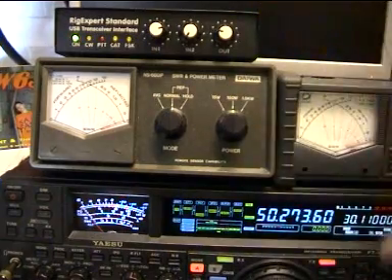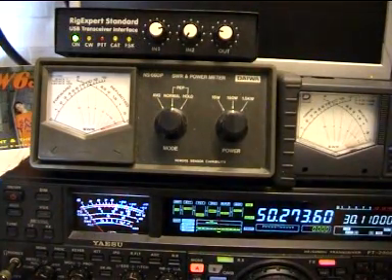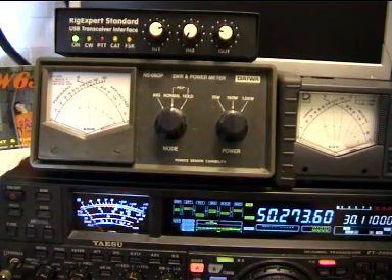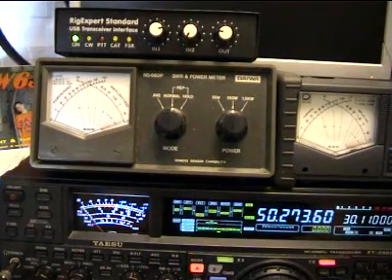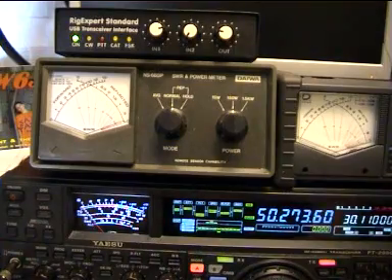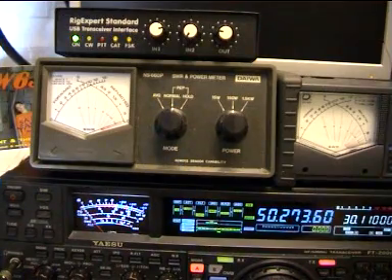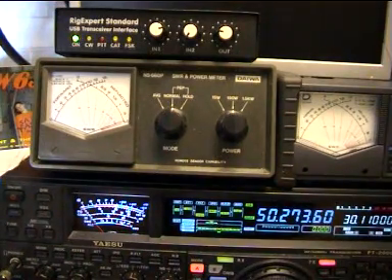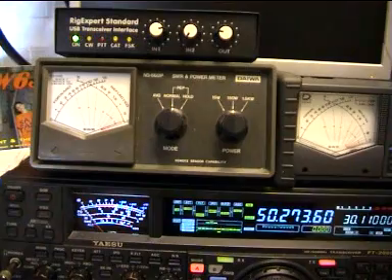Please now take your radio to an unoccupied frequency, or better still, into a dummy load. Select the output power that you intend to be using. So should that be 50 watts, 100 watts, or possibly 400 watts, depending upon your particular setup. It's very important that you set the ALC up for the desired output power, as if you adjust the ALC and then change your mind and run a different output power, it is entirely possible that you may then be running too low or too high an audio output, and could possibly risk running distortion if your audio levels into your radio are too high.